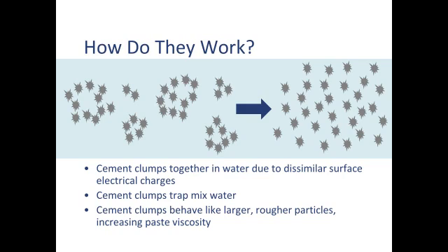So all these little tiny particles are influenced by the fact that they're in water, and water's a polar molecule, and these individual chunks of cement attract water to them, and they get an electric charge, and they tend to stick together, and they form these clumps. And so on the left side of the screen, I've drawn schematics of these large, spongy, open, almost like bubbles of particles stuck together. And these clumps, I should say, can trap mixed water inside them.